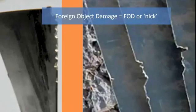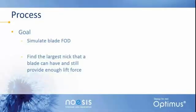So as Mark mentioned, here are a few examples of damage that can occur to these blades. The damage is referred to as foreign object damage, or FOD, and it's generally referred to as a nick. So that's what we'll be talking about and simulating today. Our goal in the case study is to simulate the FODs that occur on the blade and to calculate the aerodynamic lift force so that we can eventually find the largest nick that a blade can have and still provide enough lift force to keep the jet engine in balance.